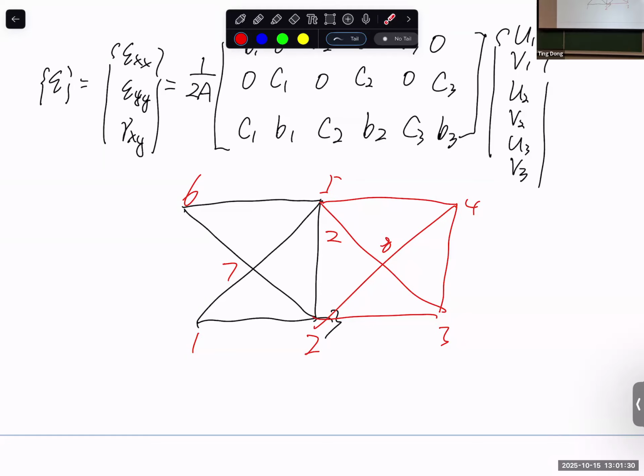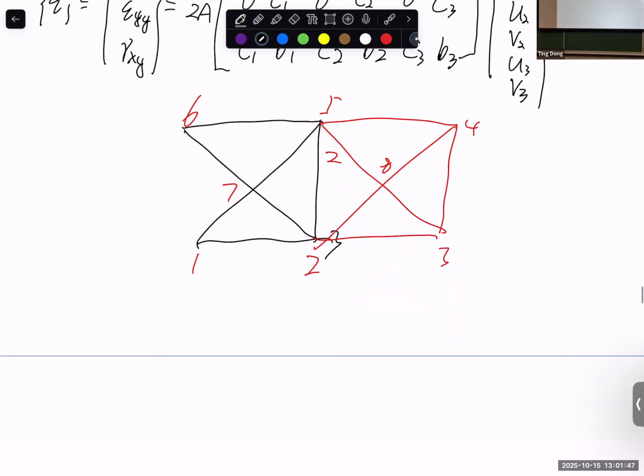Yes. But of course, that's a great question, because you can also say it's von Mises stress, because in this truss situation, sigma XX equals von Mises stress, right? Because let's say you have a stress state matrix, sigma XX, sigma YY, sigma ZZ, and this is sigma XX, with YY and ZZ equal to 0, and you don't have any shear stress.